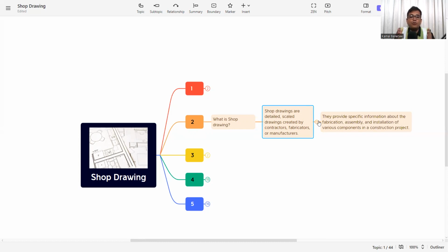Suppose you have to do a column or a shear wall in concrete. In the construction drawing or GFC drawing, it will show M30 concrete for this shear wall. Now, at the site, we cannot cast it in one go. Maybe it's 4 meters in height, so we do not cast 4 meters at once. We need to do it step by step. So what will be the steps? Where will you provide construction joints, and how will you provide them? How many lifts will there be, 2 lifts or 3 lifts?